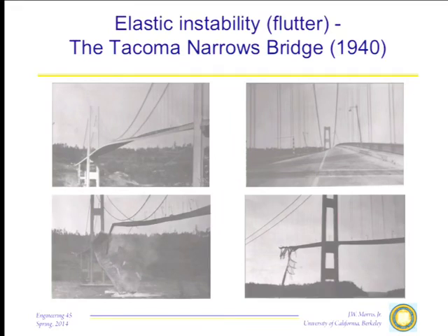And as a consequence, we had periodic failures. It was always dangerous to fly a new airplane because you just didn't know if they'd caught the harmonics or not. In the Lockheed Electra, it was the wing. In the British Comet, it was a pulse mode of the body itself that caused a number of cracks. In fact, it destroyed the British aerospace industry for a while. That again was a vibrational instability.